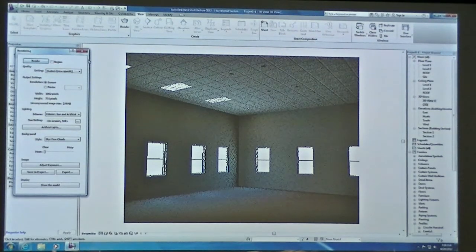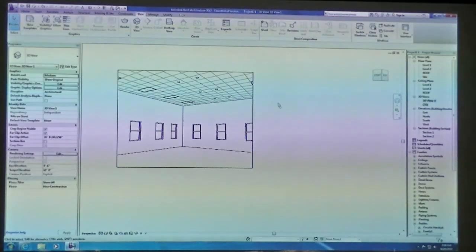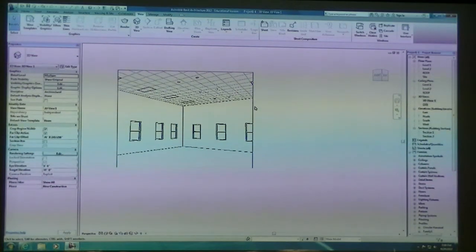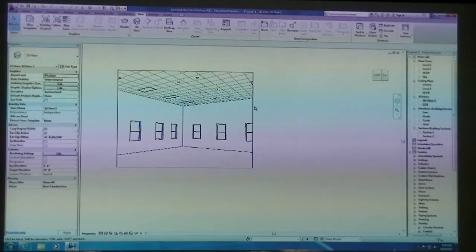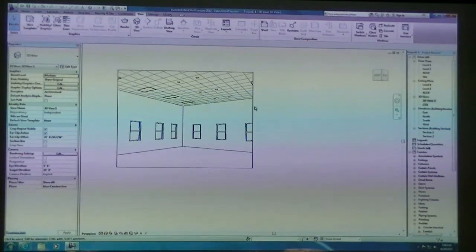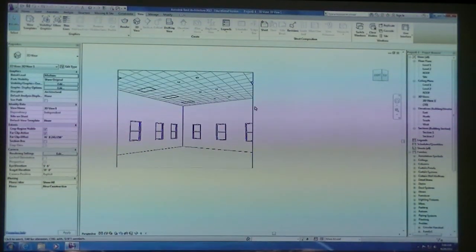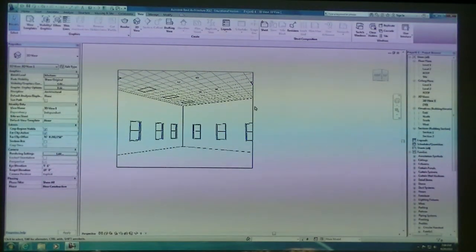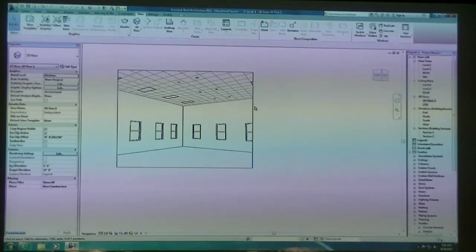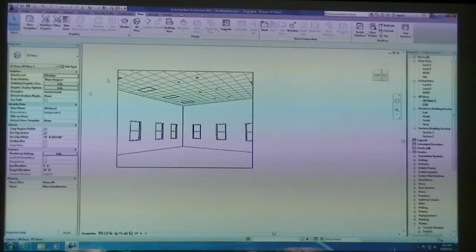Now, some tips for you on rendering. Revit uses the Mental Ray rendering engine, and it's going to render your entire model for every view that you do. Some tips on how to speed up your render times, especially since we're dealing with skyscrapers: in your visibility graphics, while you're in this view, turn off all the different components that you can't necessarily see outside of this view.